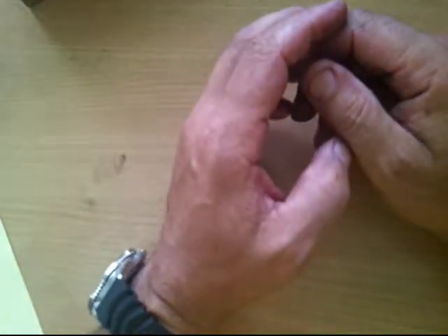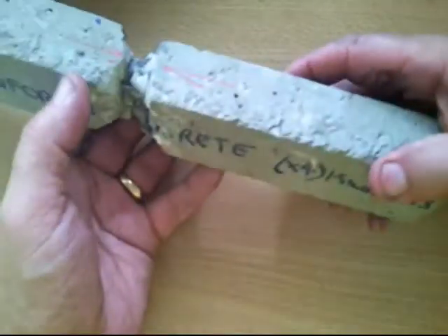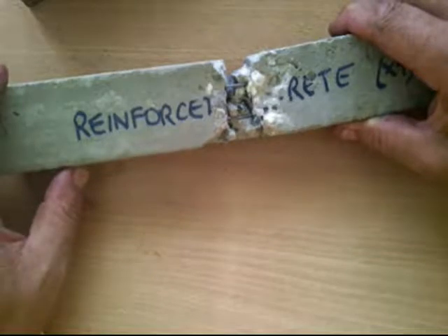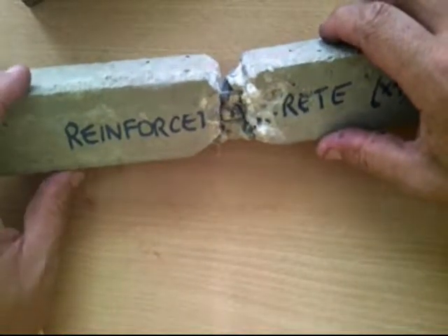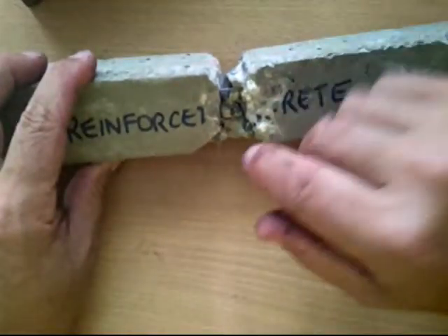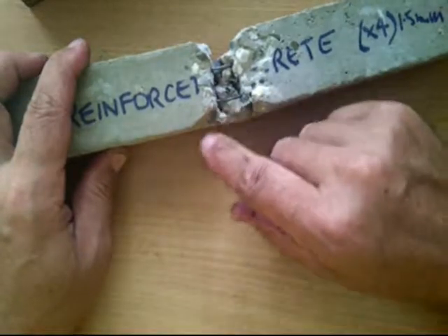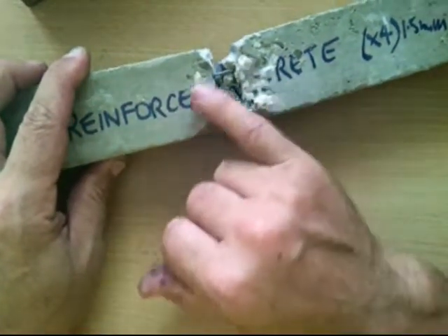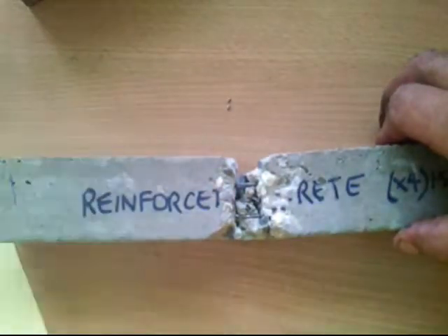Okay, some more historical use. Now, it's probably very good at this point in time to talk about concrete, seeing as we're discussing it, and have a look at modern uses of concrete. And this is a little model of a beam, and you may be able to see inside the beam here. It is a composite structure because it has more than one phase. And in this case, you have metal placed inside there, the reinforcing metal over there, and we have some concrete set around those metal reinforcing bars.